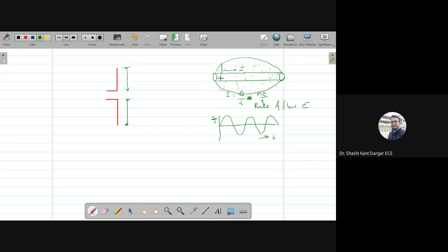Because of this positive and negative movement, the electric field has E1 and E2 fields, and after this negative half cycle, it changes. If we talk about only one half cycle, a dipole has two poles, one here and another here, and in between these two is a total wavelength. Wavelength means that if one cycle is here, the span in between is the wavelength of the cycle, from any two corresponding points. For half of the cycle, or half of the wavelength, it changes its polarity. That's the fundamental of a dipole.